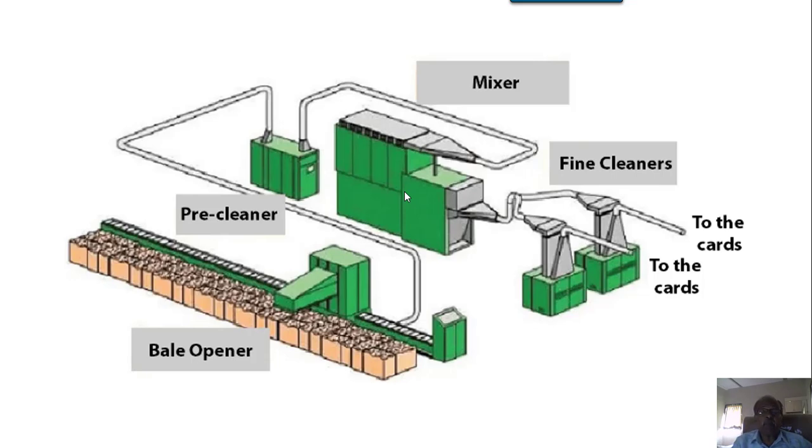And then further, in the end, that particular cotton, mixed thoroughly, will fall on a conveyor at the bottom, and each compartment will stack the cotton on that conveyor. From there it is taken ahead, and on its way out it is beaten by a beater, and then it is taken to the intensive or fine cleaners, where gripping and beating take place.